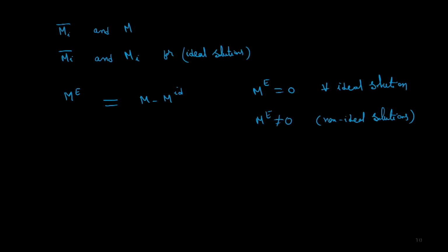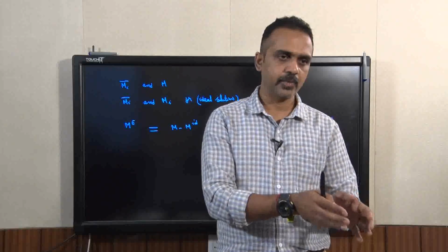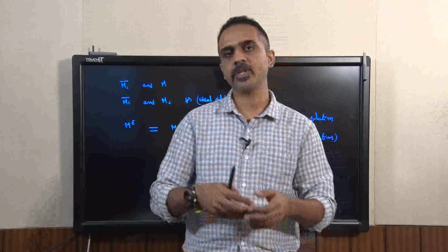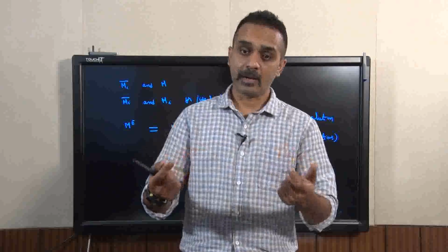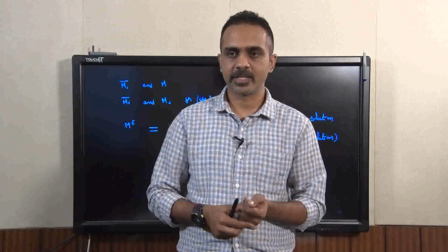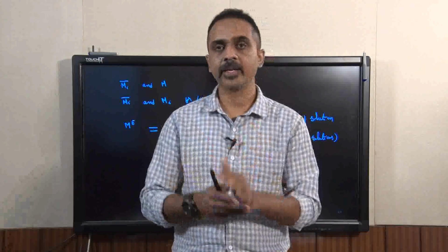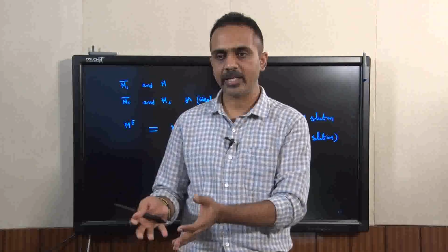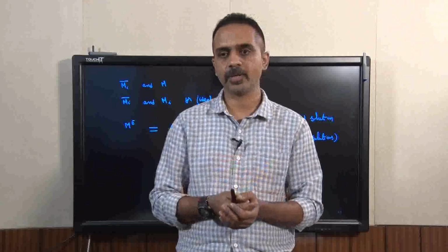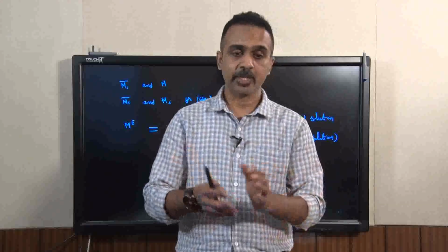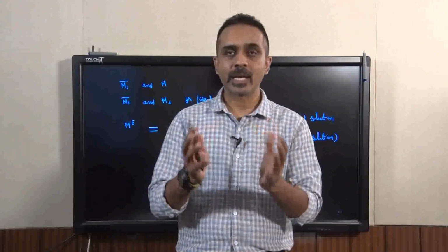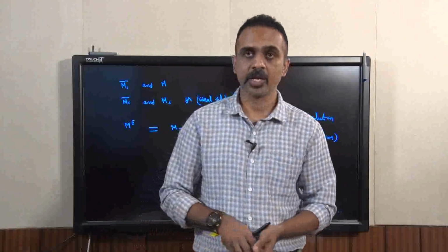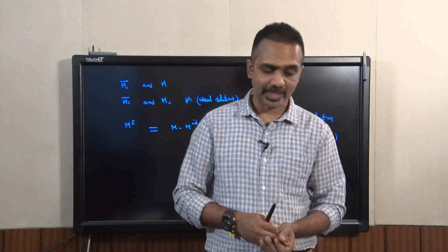Then the next thing we want to do is, there were ideal gases and then we have non-ideal gases. We have defined residual properties to characterize non-ideal gases, and we used equation of state, Pitzer correlations or Lee-Kessler tables, etc., to obtain residual properties. Similarly, how does one obtain excess properties? If I have an ideal solution and I want to quantify thermodynamic properties in non-ideal solutions, we need some information about the excess properties if we are going to take this route. So how does one get excess properties?